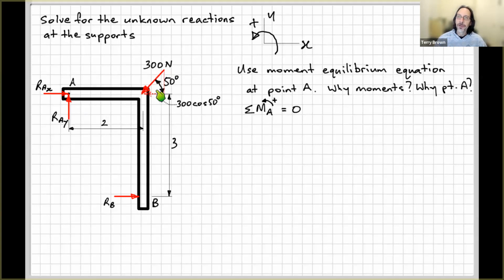And usually if we have a force at an angle, something like this, it's usually easiest to find the components of the force because usually we know these horizontal and vertical directions. So here we know this vertical distance here is 3, we know this horizontal distance here is 2. So finding the horizontal and vertical components of this force and using Varignon's theorem or the principle of moments is usually easier for most people than trying to find the perpendicular distance of this force's line of action to point A. In this case, it's not that difficult, but we'll carry on with finding the components.